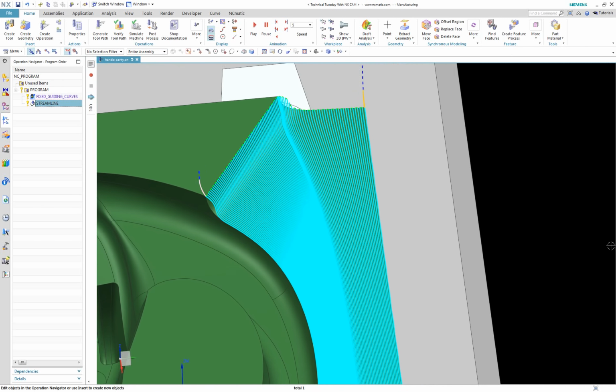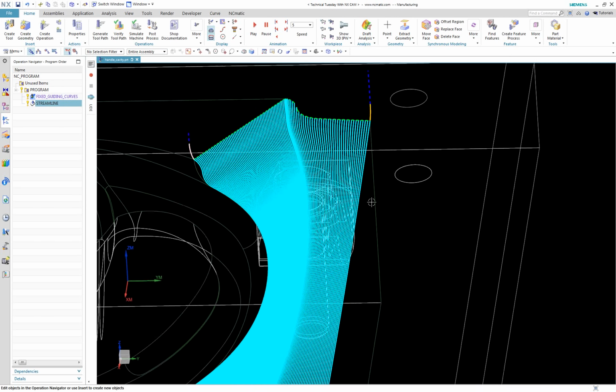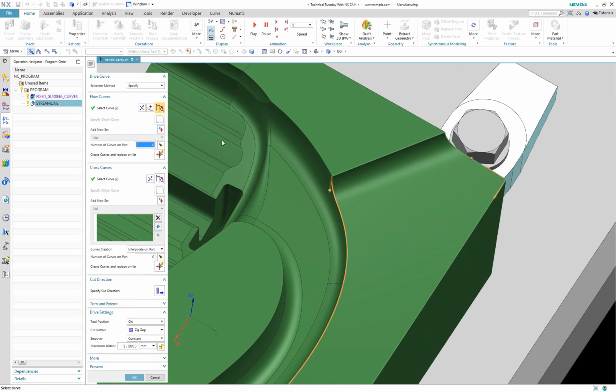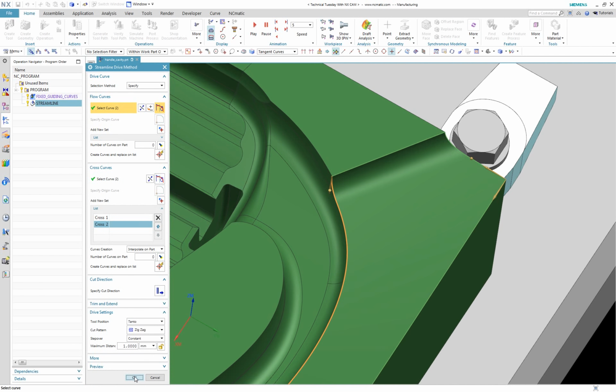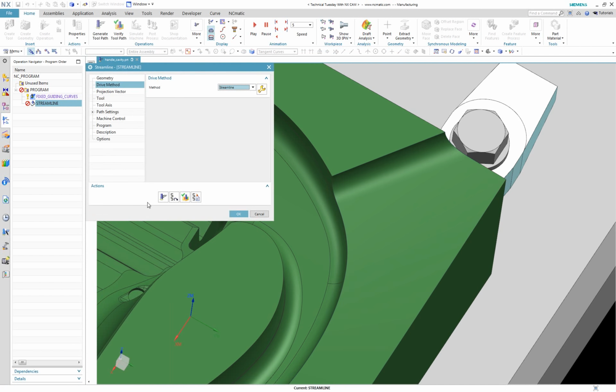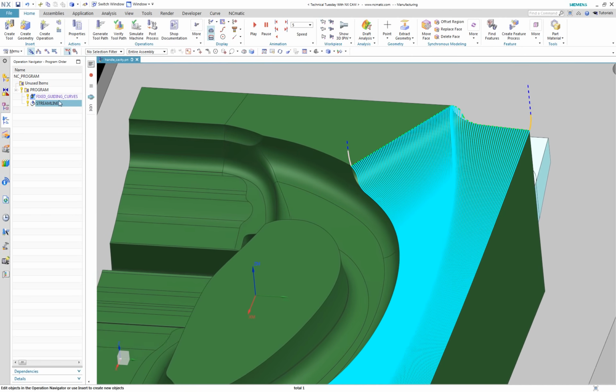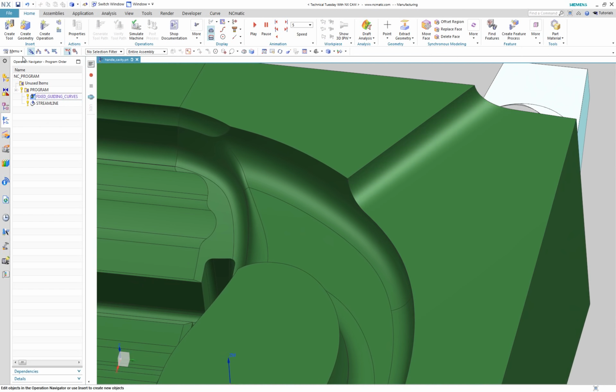We can see that with the Streamline operation, the step over value is a little inconstant. And the default tool position is set to on. Let's try it with Tangent. With Tangent tool position, some part of the cut area is skipped, so I will leave it with the on position. In this case, guiding curves operation produces a better toolpath than Streamline, and it's easier to create.